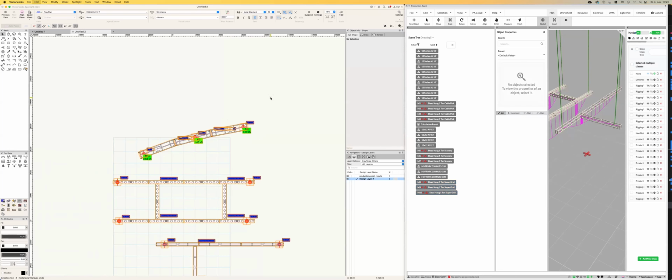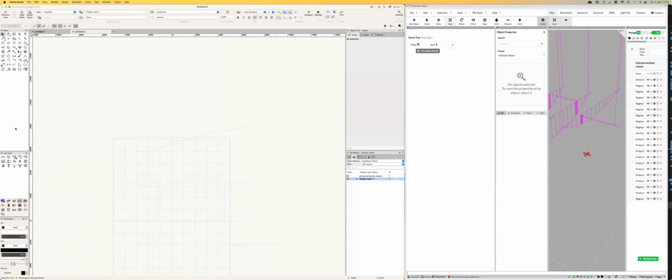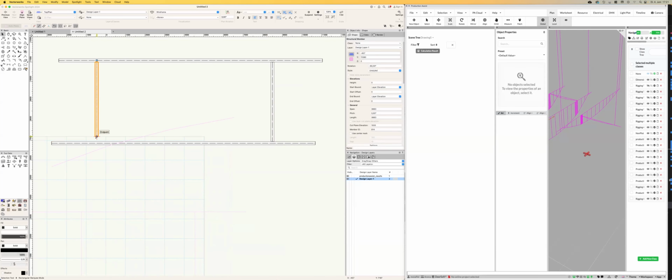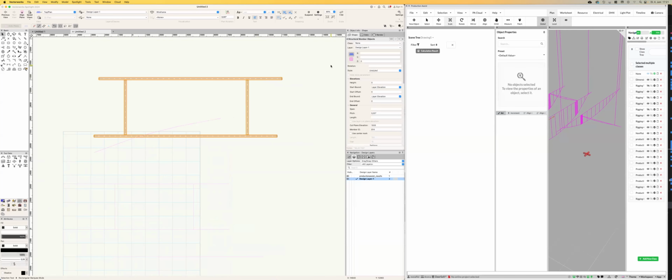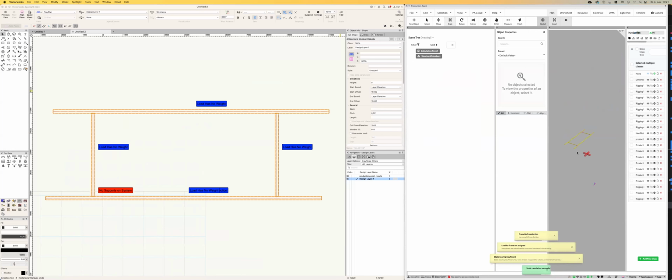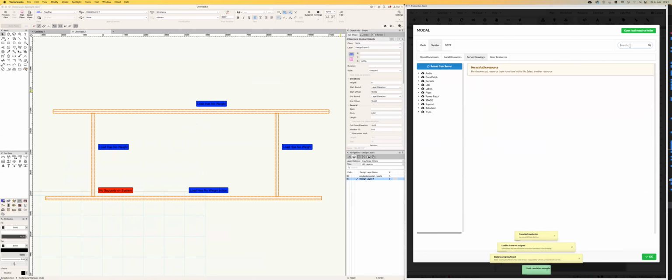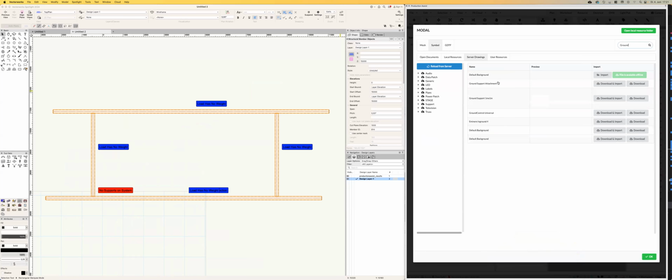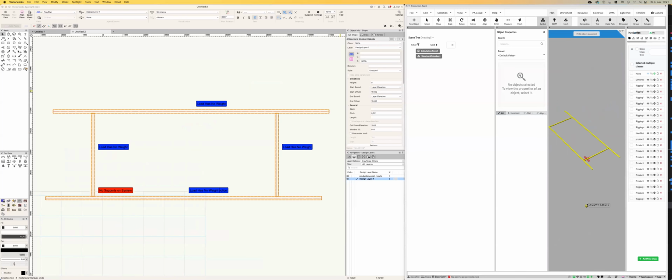That is something that you need to consider in here so that you actually can calculate it. The next thing that I wanted to show you is the new beam force simulation that we have. I quickly show you what this is. So if you're drawing some kind of pre-rig in here, move this to the right to a height of 15 meters, press OK. You can import this into production just by clicking on Vectorworks integration, import structural members. That was possible before.